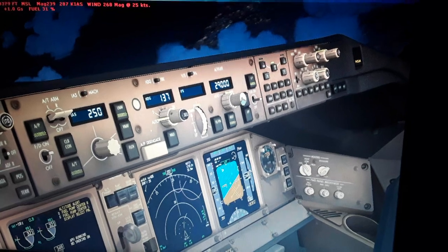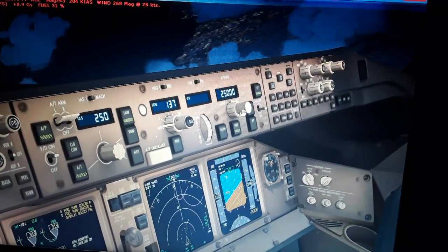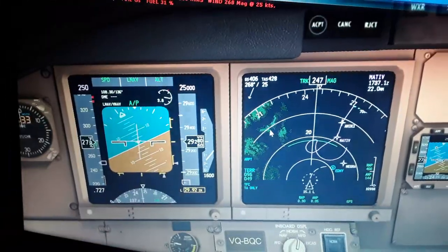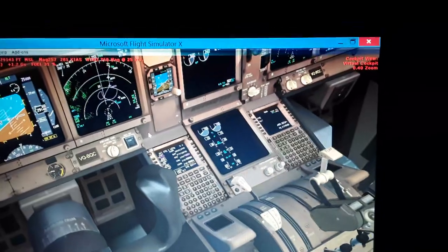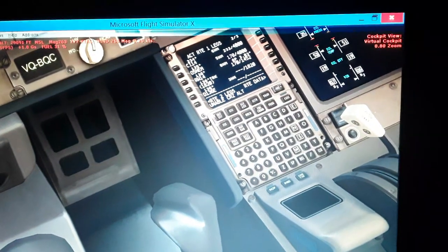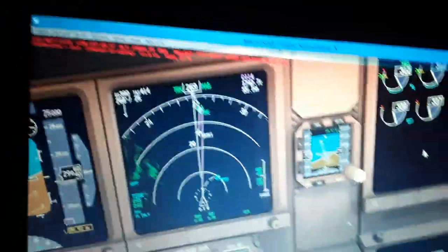We're gonna see, and also the button here, 39,000 feet. Then decrease the altitude to 35,000. We press the switch so we descend a little bit. This is the autopilot message here, connected. So maybe going direct into the airport for saving some time. Proceed direct to and execute and fly direct into the final fix.